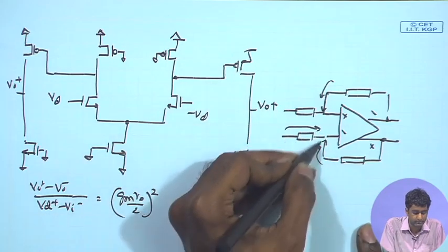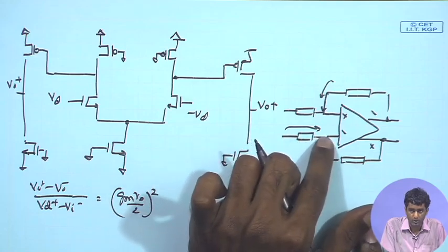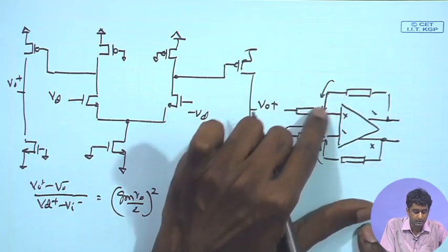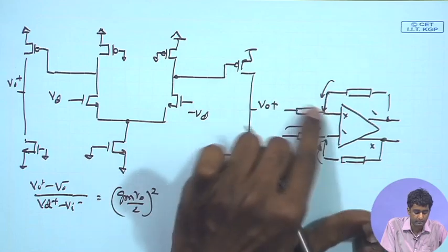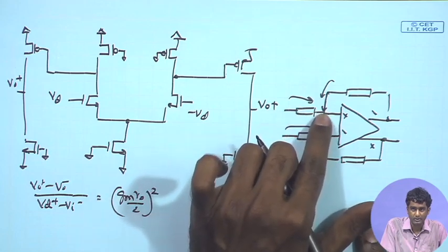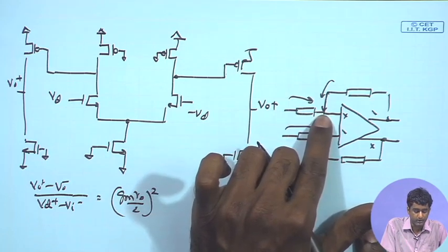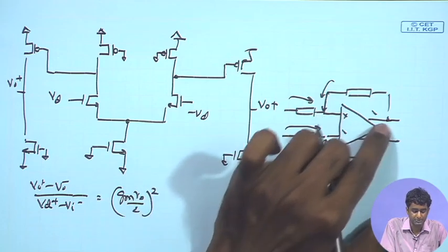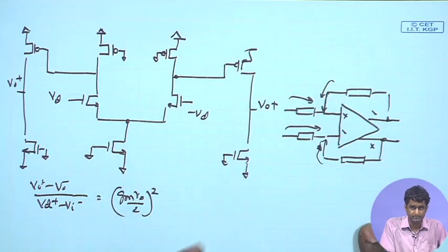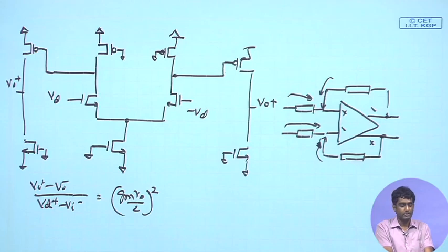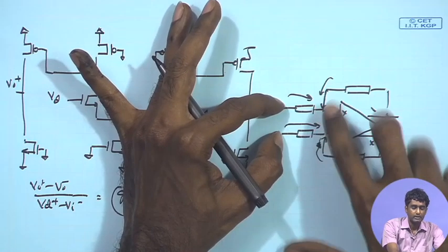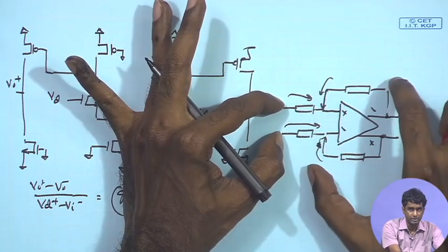So, if I have an input signal, the feedback signal is combined at the same node along with the input signal. So, if I have the signal coming from the negative terminal, it is getting combined with the signal coming at the positive terminal in a parallel fashion. So, just like we add current. So, definitely we have a shunt connection at the input, and likewise we have a shunt connection at the output, because here also we are sensing the output voltage using this feedback network. So, basically this particular topology is a shunt amplifier, although we are having an applied input voltage over here, effectively the feedback topology is like that of a shunt amplifier.